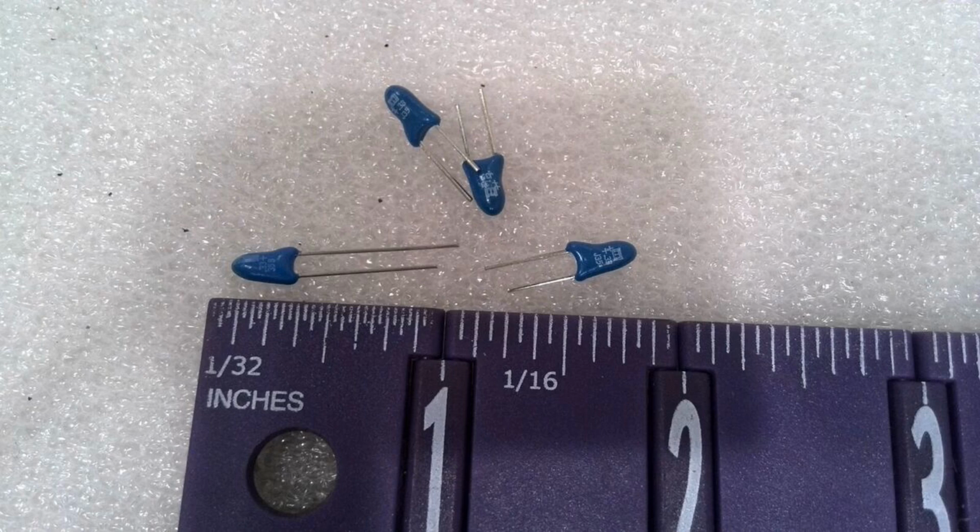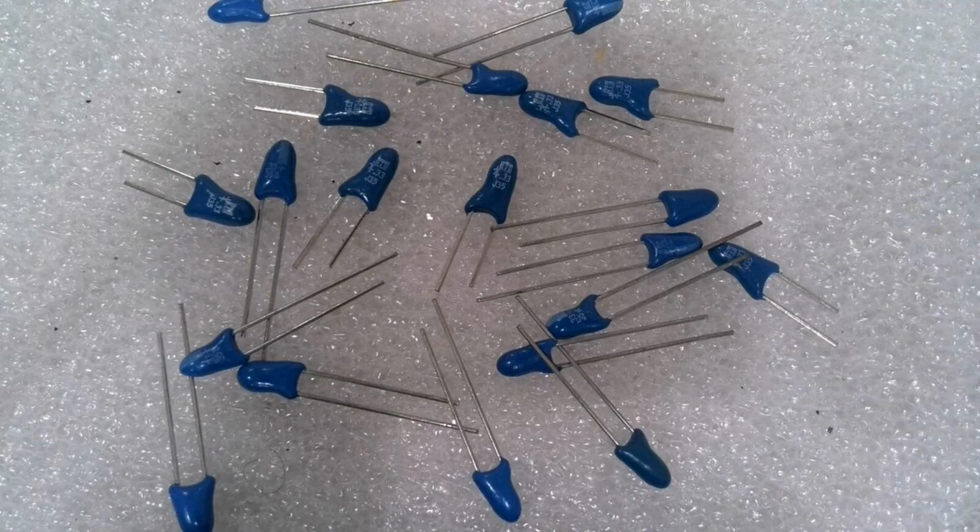8. Low equivalent series inductance, ESL. Improved high-speed performance. Tantalum capacitors have a low ESL, meaning they perform better in circuits that require fast charge and discharge cycles, such as in high-speed digital circuits. 9. Resistance to drying out. Unlike aluminum electrolytic capacitors, tantalum capacitors do not use a liquid electrolyte that can evaporate or dry out over time. This makes them more reliable and longer-lasting, particularly in high-temperature environments.